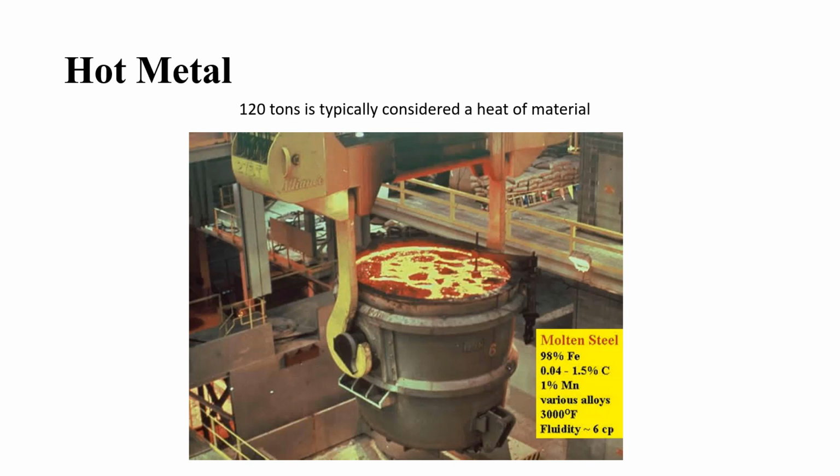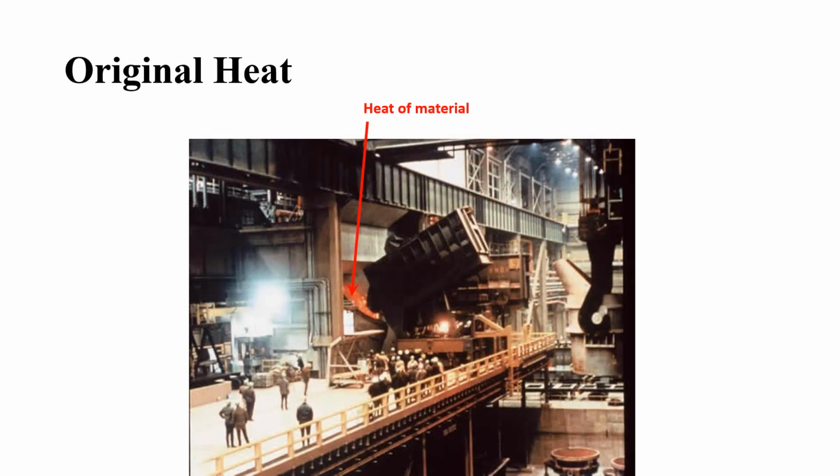of material. The various processes this ladle of steel will go through, in addition to the various alloying constituents added to it, will create a one-of-a-kind chemical fingerprint, a fingerprint specific to the heat number assigned to it. Here you see scrap being added to a heat of material along with a cocktail of alloying material in meeting the recipe for a specific type and grade of steel.